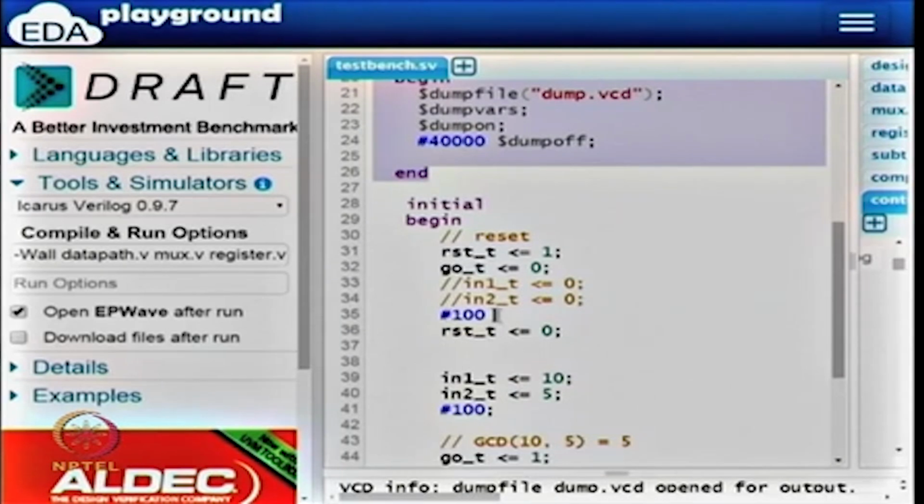Once the reset is gone, we pull down reset. So resetting the chip means bringing it to 1 and then bringing it back to 0, right. That will reset the chip. At this point all the registers will have 0, and if you remember, the state register also has a reset input. It will go to 000, and 000 is for state S0. So this will take it to state S0. At this point go is 0, which means it will loop back in state S0 itself.